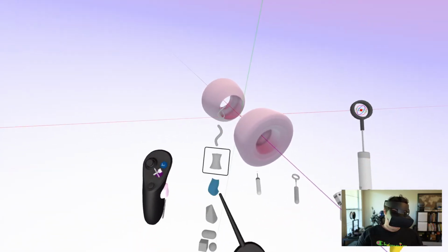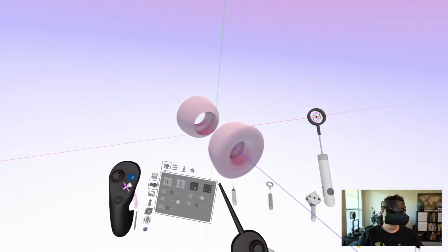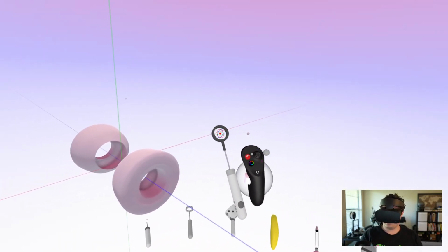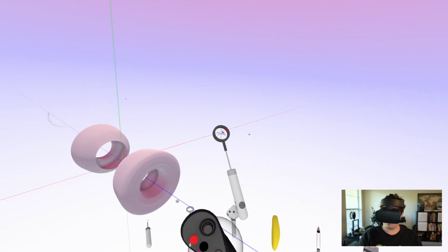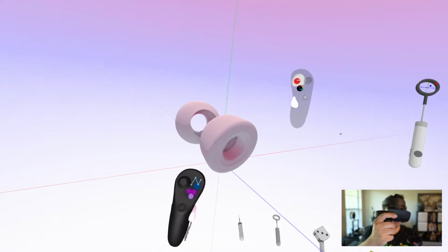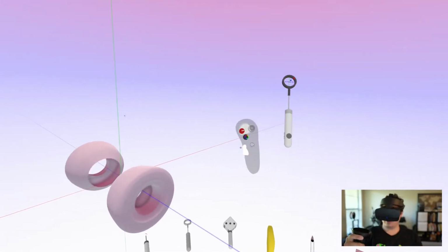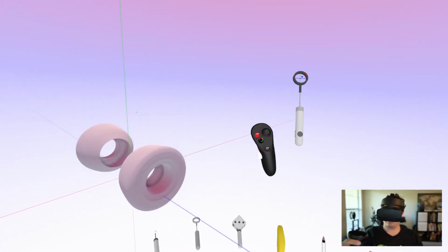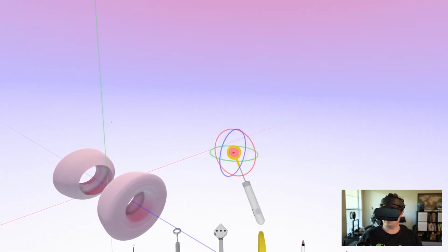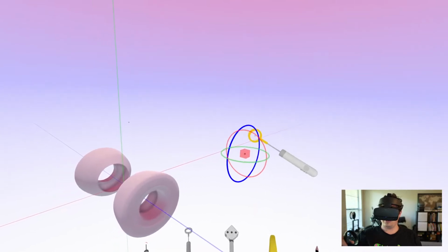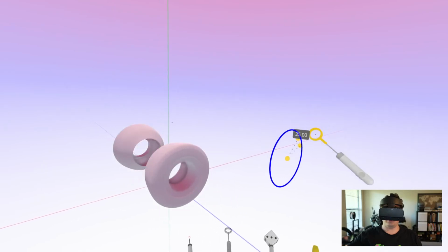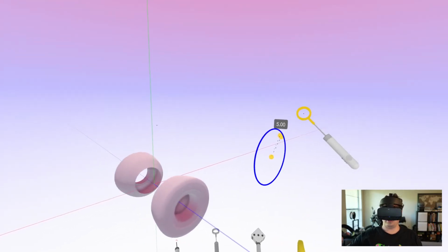If you want to do that, there's a little bit of a trick to do that. If we go to maybe like a stroke or something, we just make a little dot. Say I want it to rotate around this point. What we can do is we can select those two together. We can group them. So now they're the same object, or they're grouped together. And we can actually put our point on that. And then now we can rotate around that point in space. So that's a little bit of a way to get around that.